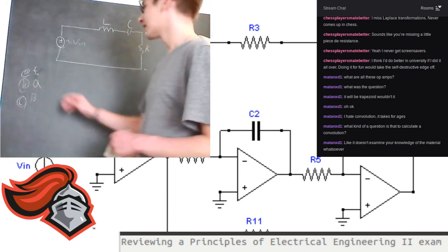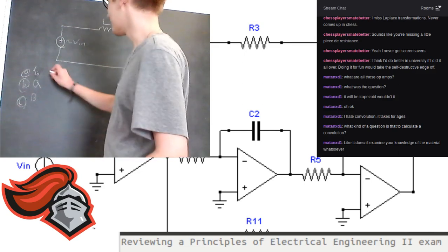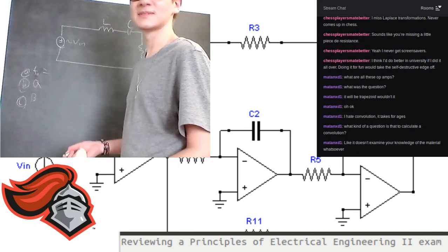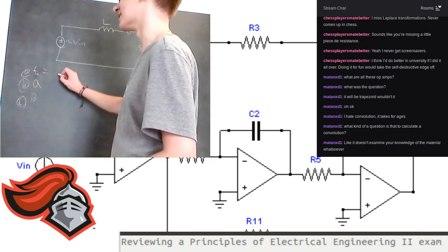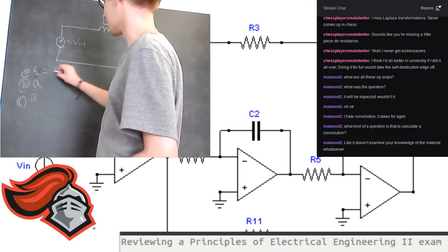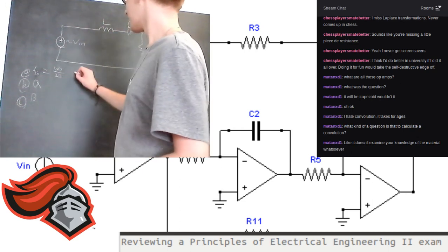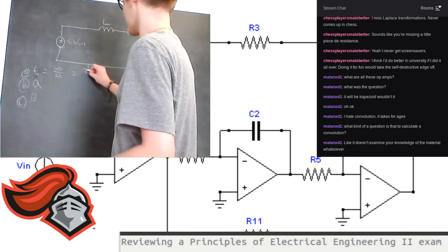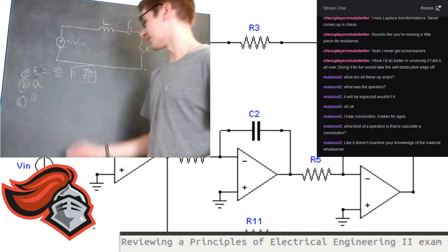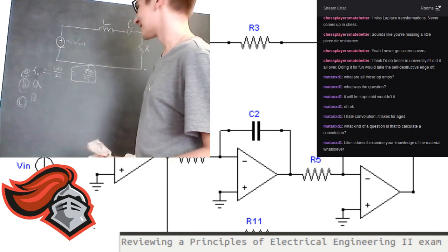Anyway, here we have the center frequency, which if you were clever and wrote it down on your equation sheet, which I think most of the students taking the exam probably did, this is just, first of all, angular frequency divided by 2 pi, which is 1 over square root of LC over 2 pi. And then this was your answer. Yeah, this problem was really just free points.